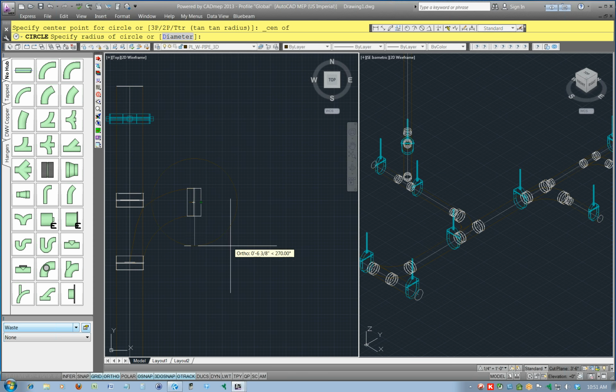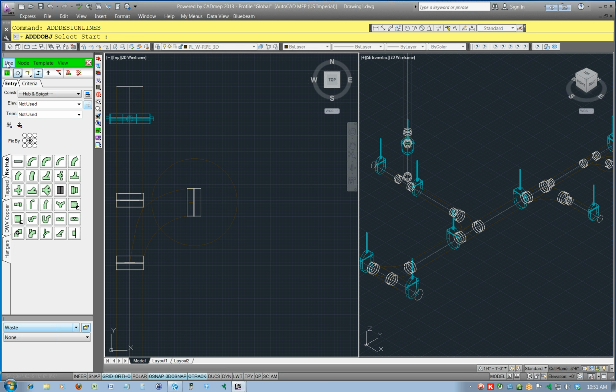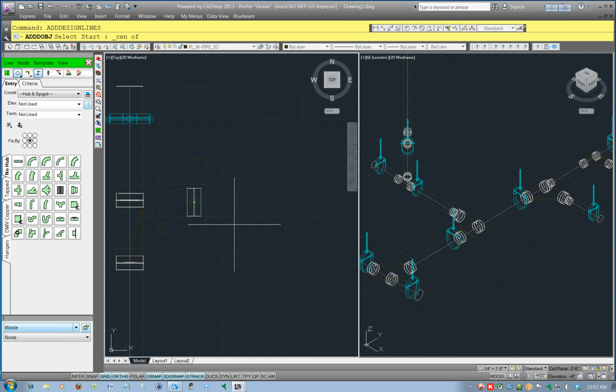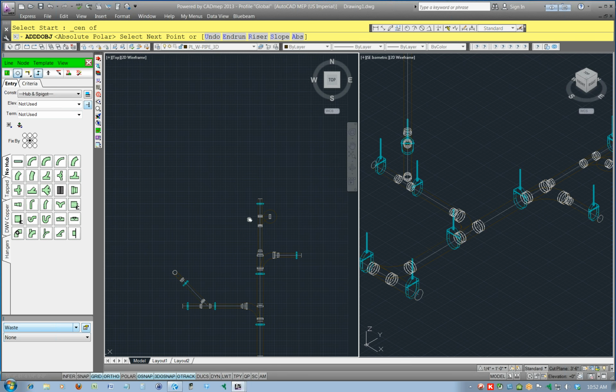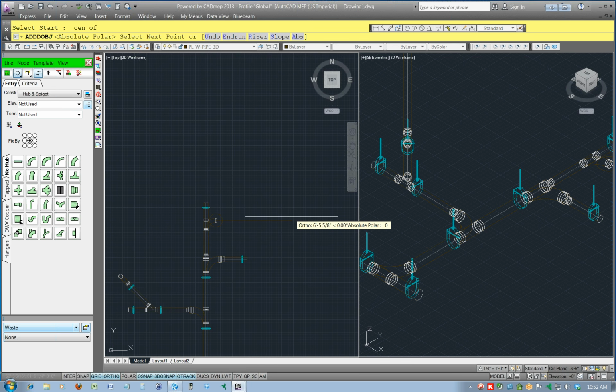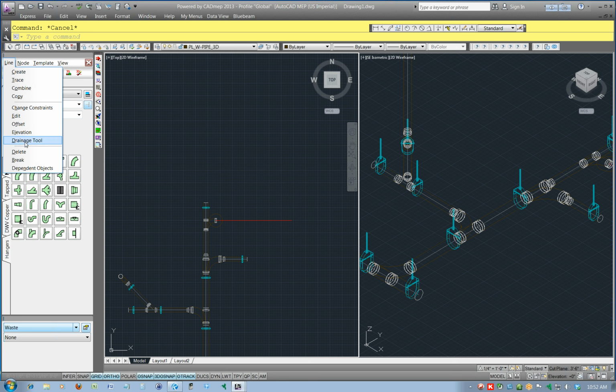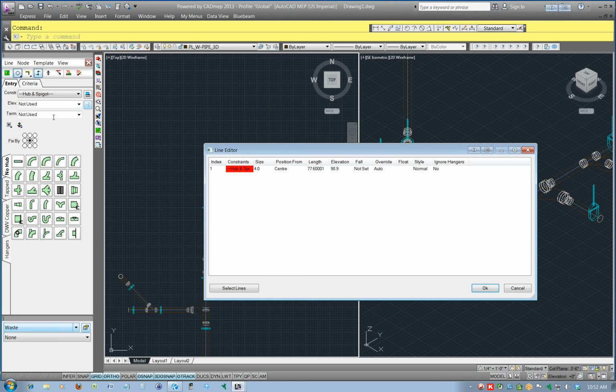So before you go in design line, draw yourself something to snap to. Now we can go in here. Elevation not used because we're snapping. And we're going to create. Now we've got something to snap to. Center. You can draw your new branch here, which I did not pick a size for, so I'm going to do that after the fact by going to line edit.